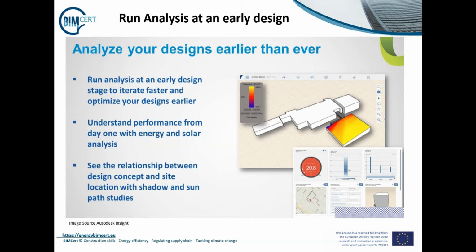Another package is called Autodesk Insight. This package takes a conceptual design and runs analysis in order to optimize your designs earlier. It provides an understanding of the performance from day one with energy and solar analysis, and one can see the relationship between design concept and site location with shadow and sun path.